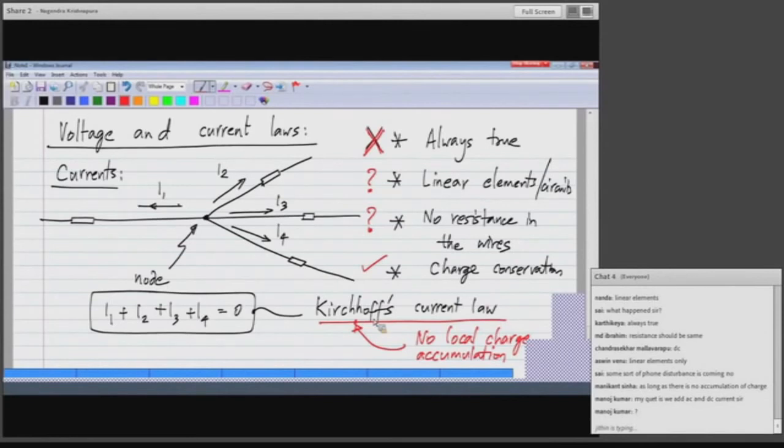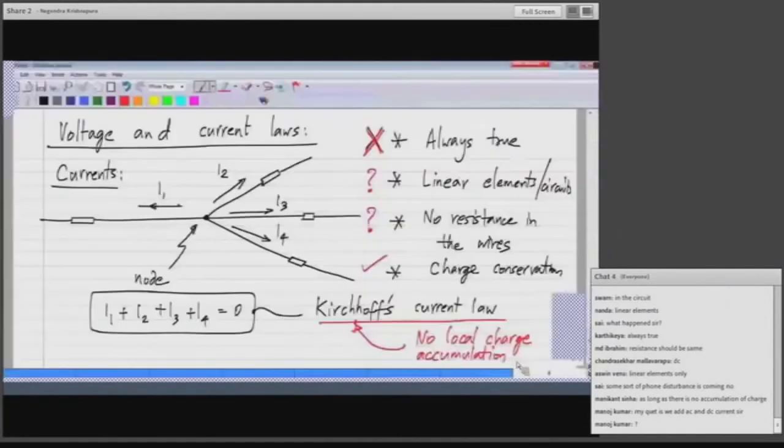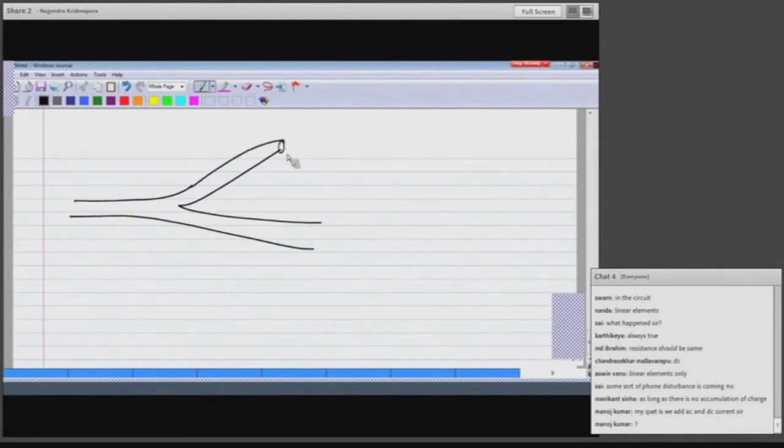Or if I have to use the convention for currents, I took all the flow to be away from the node. So, I can also take R1 liters per minute flowing that way, R2 liters per minute flowing this way, and this way it is minus 10 liters per minute. It's a slightly weird way of saying it, but a useful way when you talk about currents. I initially assumed that the flow is that way, but it turns out that the flow is from left to right, so that means from right to left minus 10 liters per minute are flowing. So, minus 10 plus R1 plus R2 will be 0. This is something that you intuitively feel is true, even without knowing a great deal of fluid dynamics and so on.